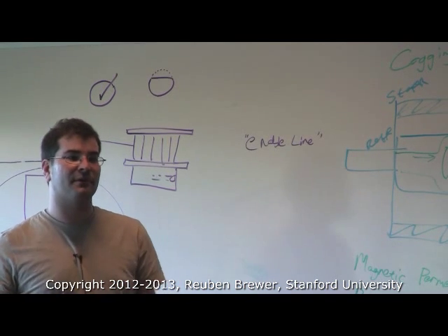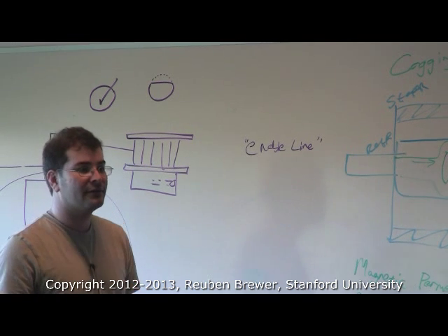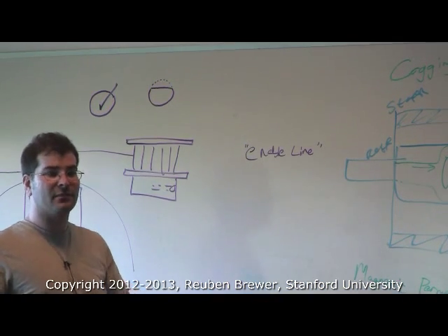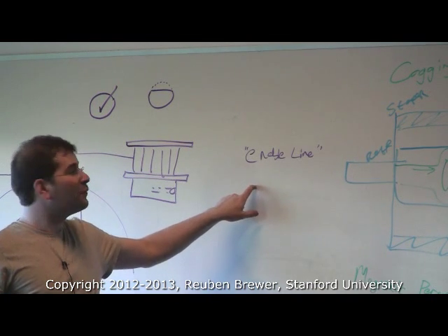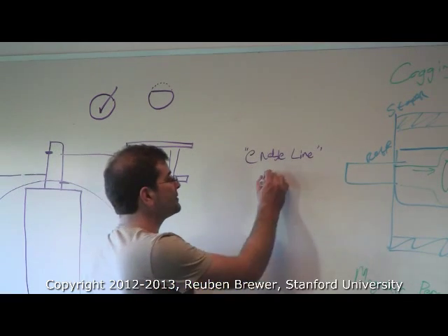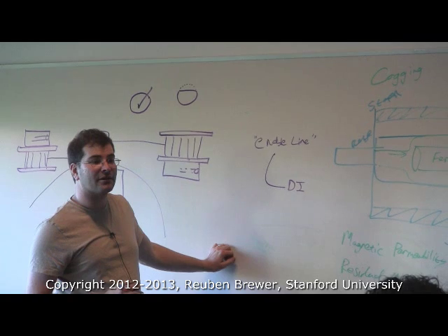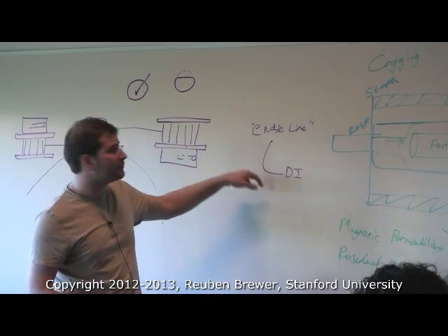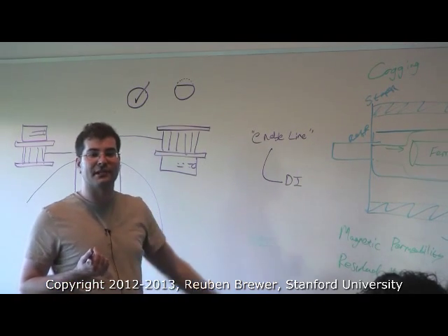Oftentimes they have 2 separate ones. They have an active enable line and they also have a disable line. If you're not pressing the enable line, or conversely you're smashing the disable line, everything shuts down. And this isn't in your computer. What happens if we read this into a digital in on our computer, and our computer froze, and our robot was stuck on, and we're smushing the button, and the computer doesn't care because the DAQ card froze? Thank you, National Instruments and Linux.